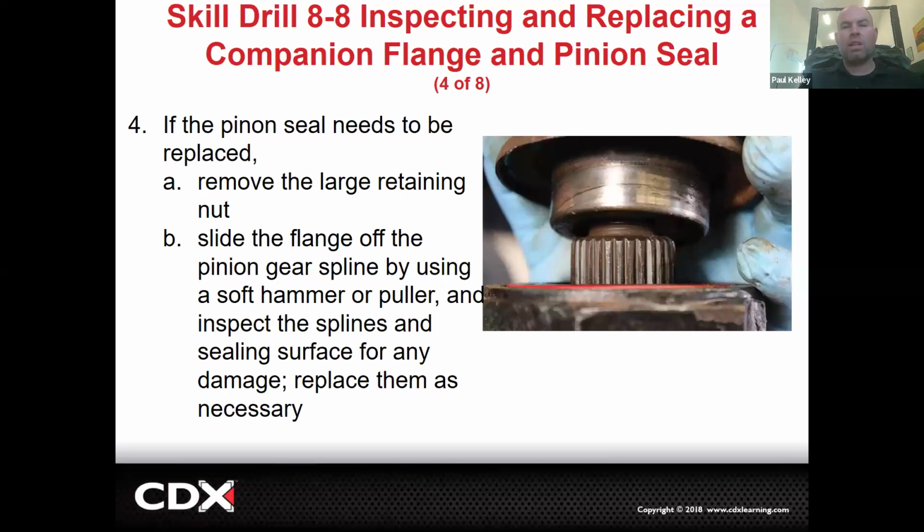It came back like a week later, and the whole pinion had been slopping around like this, messed up the teeth in the ring gear, and ended up nuking the pinion bearings. That diff basically blew up. And it blew up because he over torqued it and then he under torqued it. And it all started with a pinion seal. So they were kind of like, hey, did you not know? Did you not have any idea? And he's sort of like, I don't know.